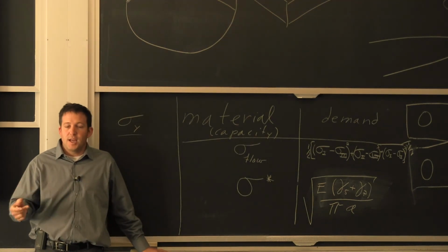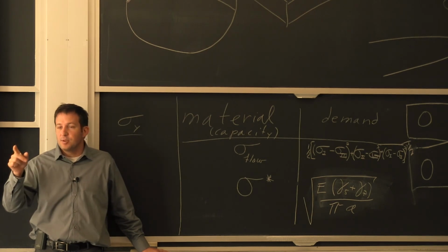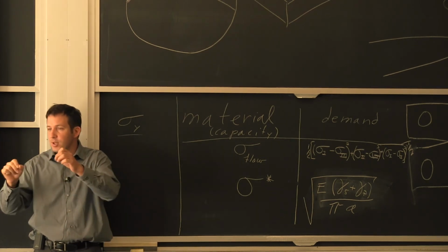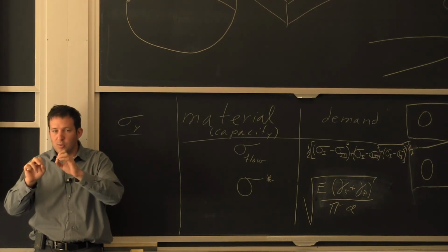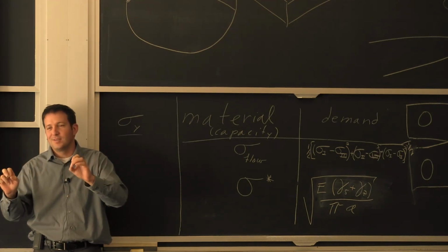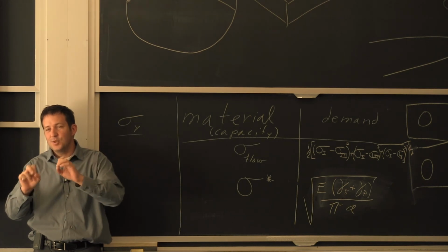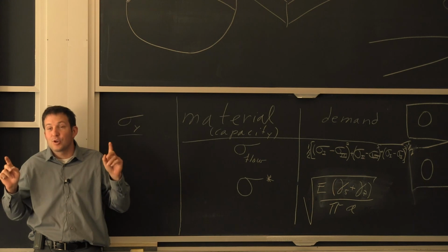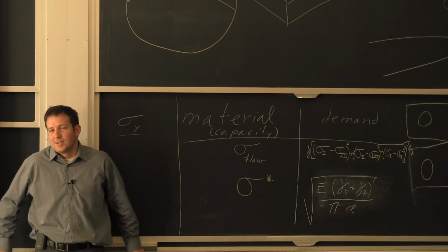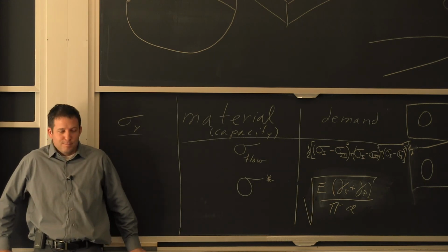You can have one area, say one time, this is going to be almost like a tensile test. I'm pulling on it, and then I'm done. It gave me what I needed, gave me 1% strain, that's all I wanted. If your material can't give you 1 or 2% strain, most of the time it's not really considered structural material anymore. So that's kind of my pitch on that.